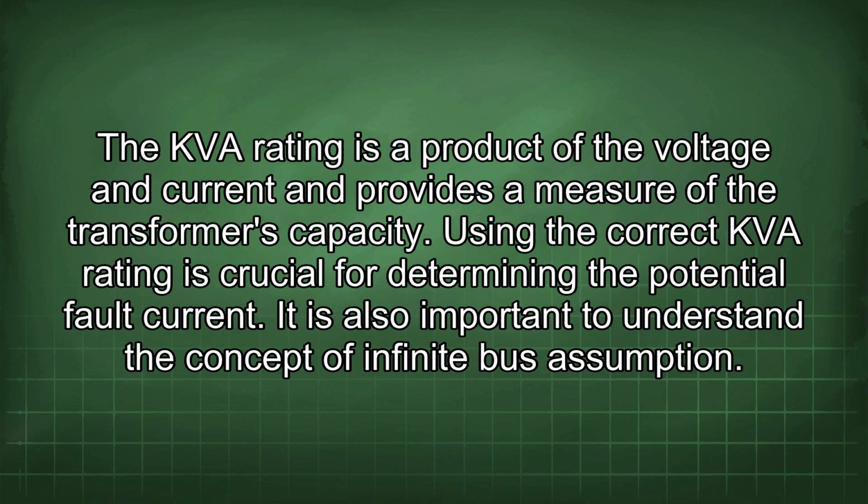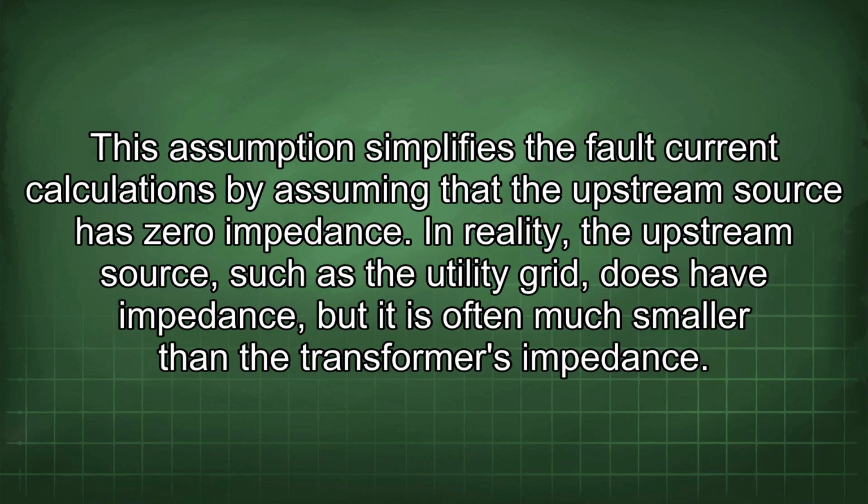It is also important to understand the concept of infinite bus assumption. This assumption simplifies the fault current calculations by assuming that the upstream source has zero impedance.